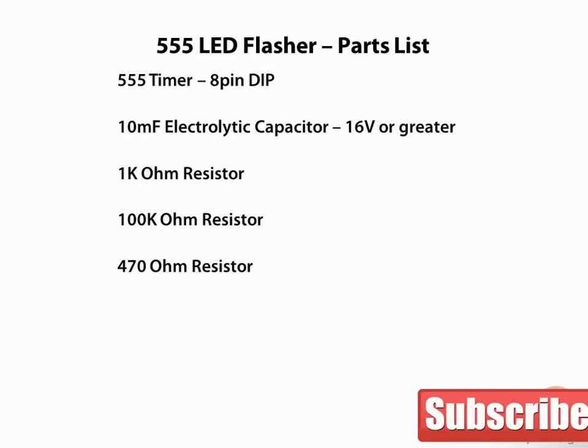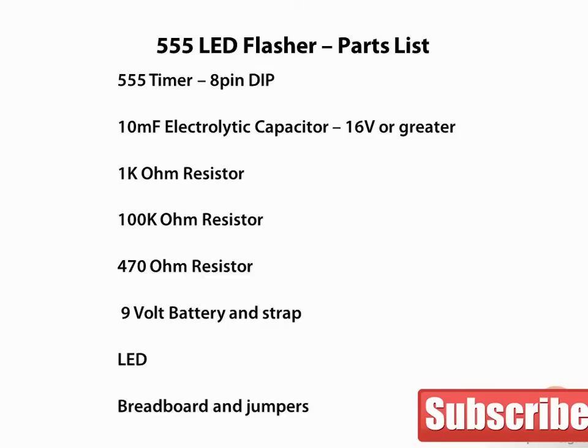All the resistors, their wattages aren't real important. We're not passing a lot of current through them, so your standard 1/8 or quarter watt resistor will be fine. We'll need a 9-volt battery and a battery strap. And of course, we'll need an LED. And we'll need our breadboard and jumpers. Now all our components should be through-hole components, which means they all have leads. We don't want any surface mount components or SMD components.